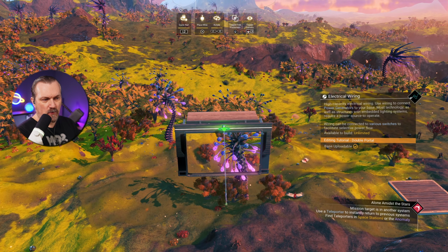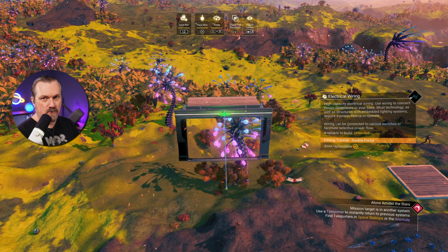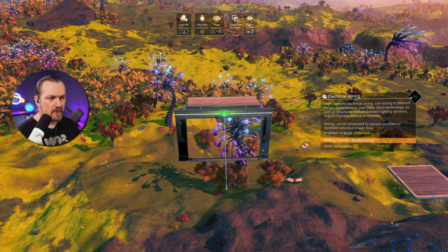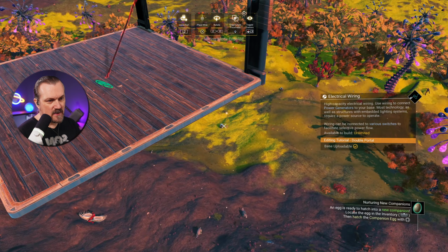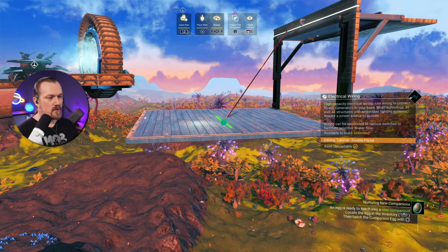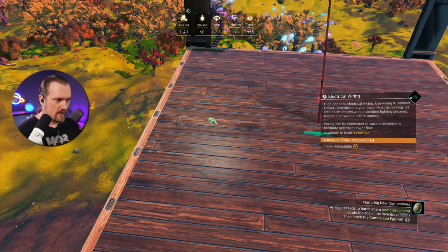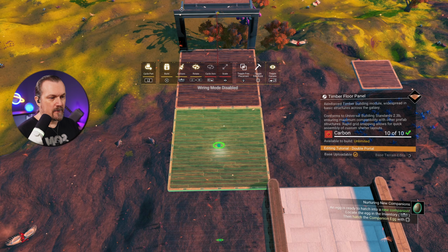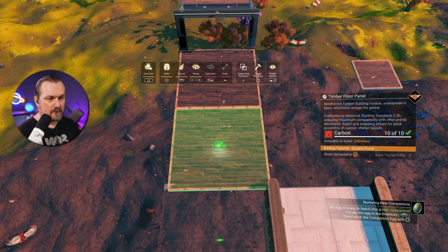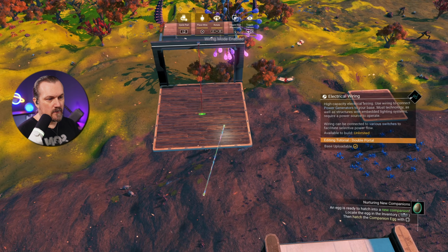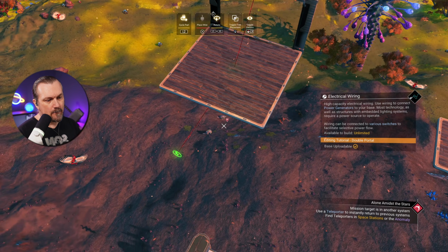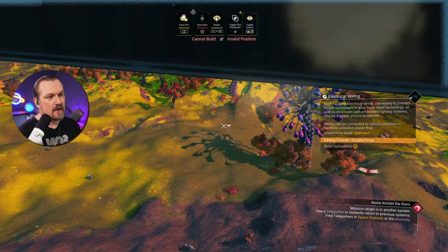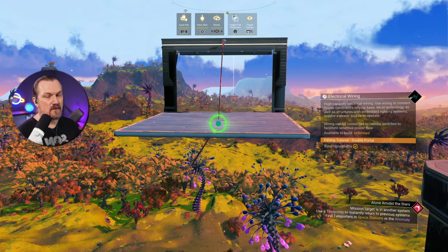Doesn't matter. You can pull it on this one or this one. It doesn't make a difference for the level wire. Then we're going to put the floor back. You can see that floor is now covering that perfect center point of that wire. We're going to take another floor, reverse wire glitch again, and then pull that one towards this connector here. And that is now a perfect level wire and also centered in the floor.